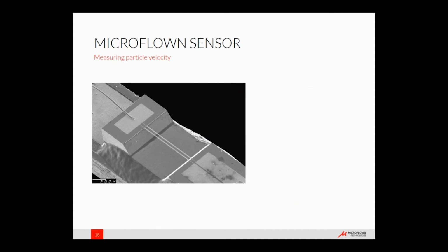Typically, if you look at a sound pressure microphone, what we look at is a moving membrane. But what we use here is MEMS technology. MEMS stands for microelectrical mechanical sensor. And this MEMS sensor we can use to capture directly the acoustic particle velocity. So what happens when the wavefront comes to the first wire? There will be a heat interchange.